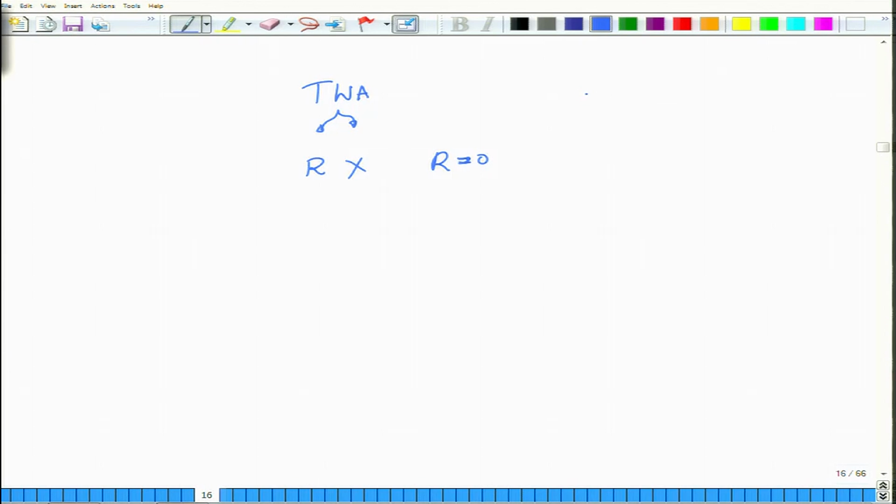In fact, you can't get R approximately 0. So, what you would actually have is a range of values of R, say from the ideal 0 value to about 0.1, let us say, wherein we would treat the semiconductor optical amplifier as a travelling wave amplifier, and beyond that we would treat it as a Fabry-Perot amplifier. So, beyond a value of R of say 0.1, 0.12, 0.15, you would deal with it as a Fabry-Perot amplifier.